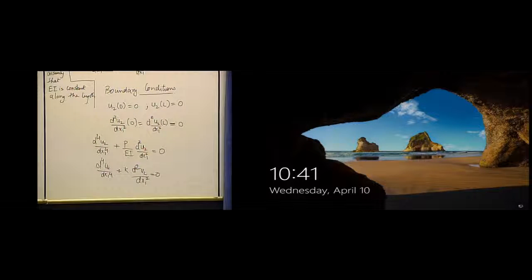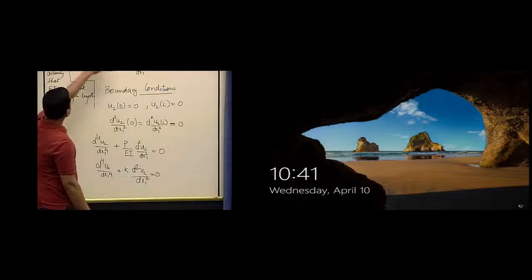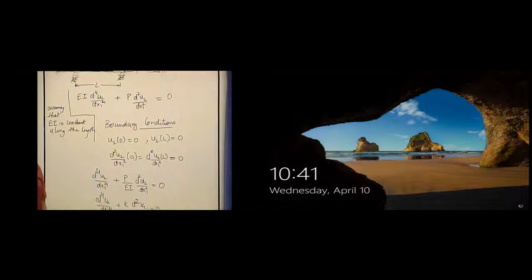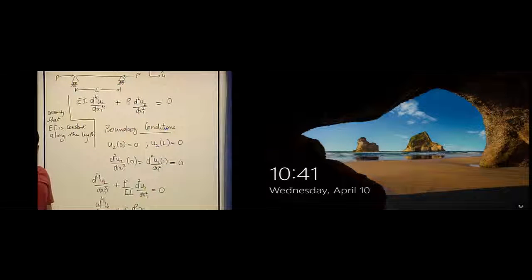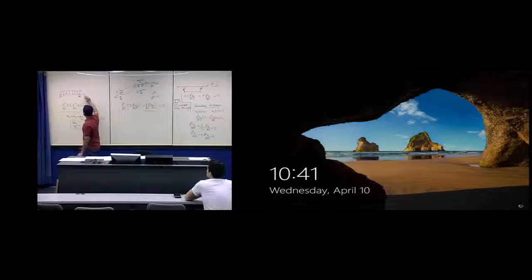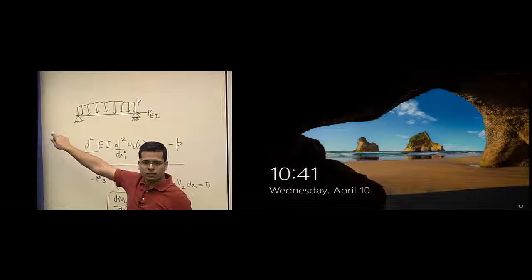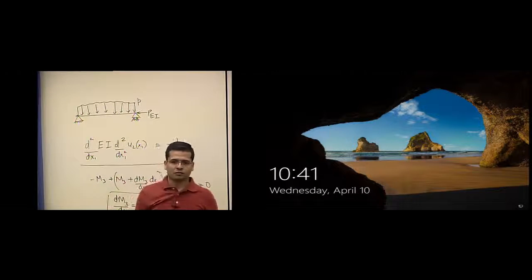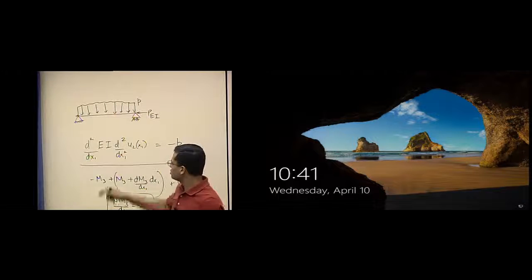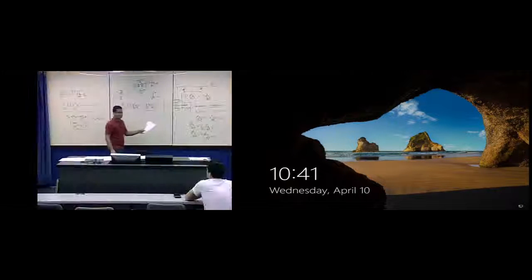Sorry, does the load have to be symmetric? So has to be P, or can it be P on one side and P over 2 on the other side? If you have roller supports, well, in this particular case, yes. If you have rollers, it will move, so nothing will happen. But if you have a physical support, for example this, then if you apply P over 2, the reaction is also P over 2 for equilibrium, right? So it will always be the same. I just removed that fixed support and replaced it with a roller and a force in this diagram.